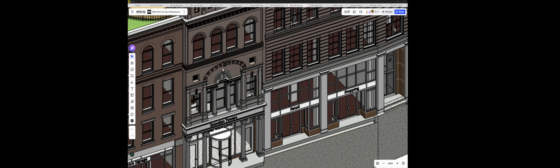So if I was doing a drawing and I decided that I want to use this window here, but I want to make it out of a curtain wall, which you can, visually it would look the same. But if you remember BIM, which is building information modeling, the I stands for information. In a traditional architectural drawing, where you have to list out your windows, you would have to manually count how many windows.